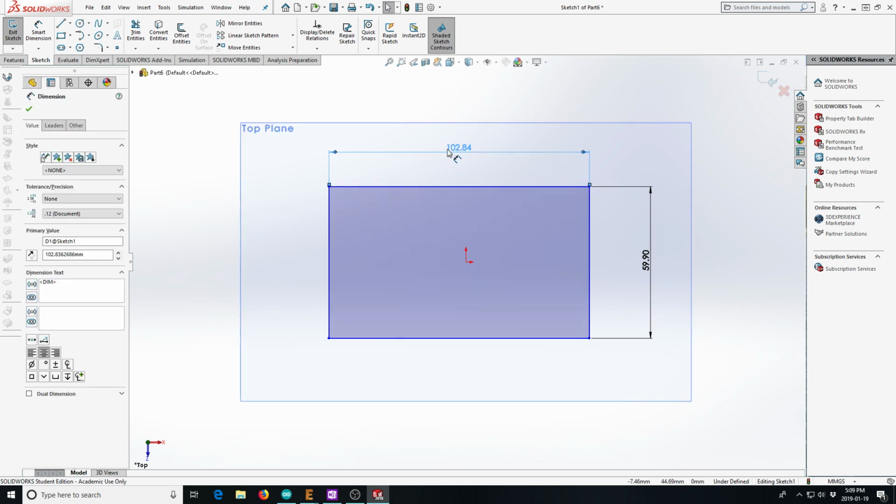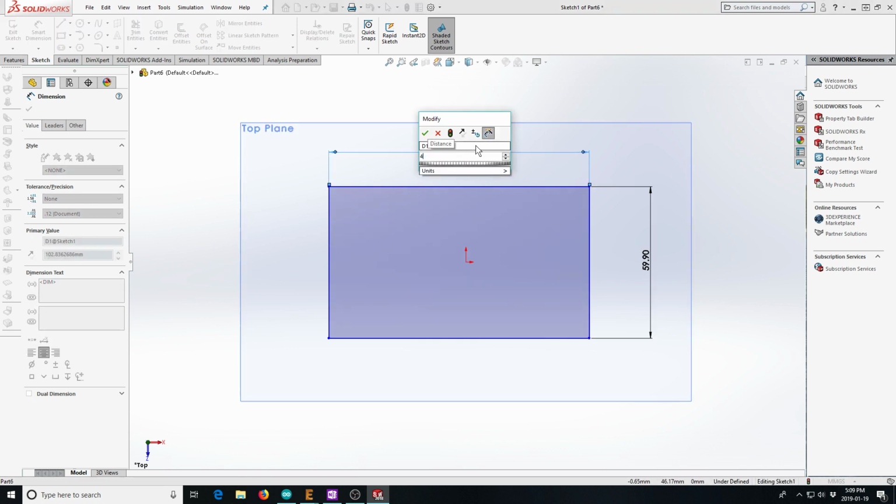So if we're going to make the short dimension of the box, I'm going to do this from the outside of the box, perhaps. You could do the inside dimensions to start off with, but I'm going to do the outside. We said 35 was the narrow side of the outside plan. If I add 5 on each side to that, that makes it 45, maybe a little bit more than that. So I'm going to maybe make it 48 millimeters.